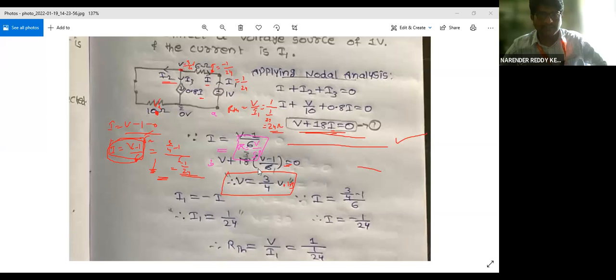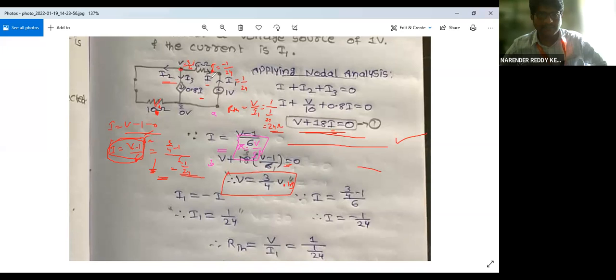You can even give a try for that. Assume that voltage to be 10 volts. So all we are doing is a reverse process. We don't know how this equivalent resistance has to be calculated. So what we are doing now is using a source and pumping current, and we take the magnitude of voltage and current which we are pumping inside and take the ratio, and that will be the equivalent across these two terminals. That's what we are doing here. We are least bothered about the rest of the parameters in the circuit when you have a dependent source. Am I clear?